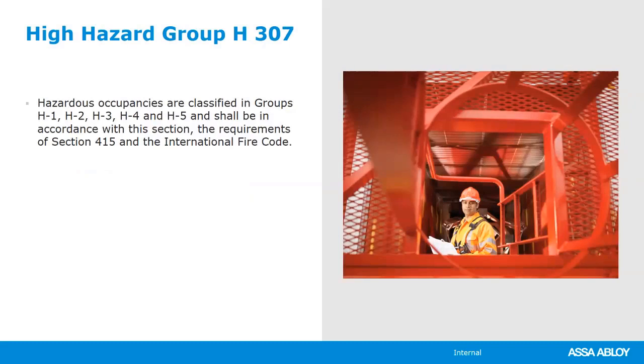High hazard is storage rooms and other types of rooms that include manufacturing, processing, or generation of materials that constitute a physical or health hazard, materials that are highly flammable or that could explode on any given contact. And so it is among the highest risk. Delayed egress is not permitted on a high hazard occupancy.